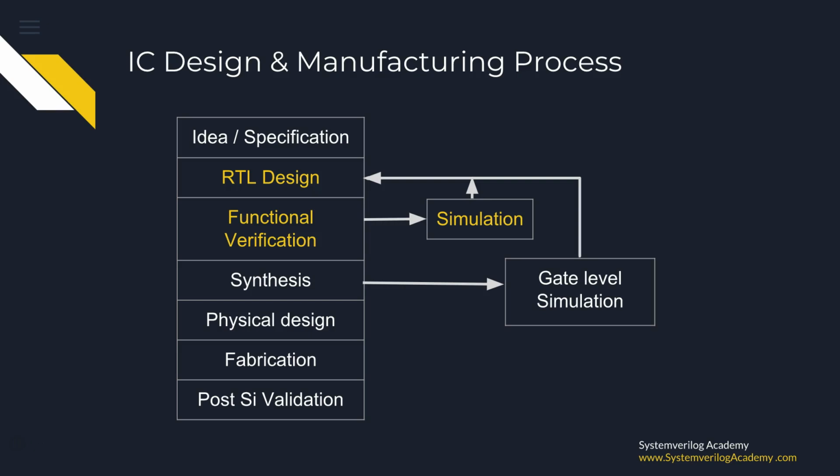The next phase is functional verification. Here, the design is simulated using an extra piece of SystemVerilog code called the testbench or TB code. The testbench will use a simulation EDA tool to inject stimulus into the inputs of the design and will check the correctness of its outputs. This will expose the issues or bugs in the design, which will be fixed in the RTL code. These phases are repeated multiple times until the RTL code is bug-free.